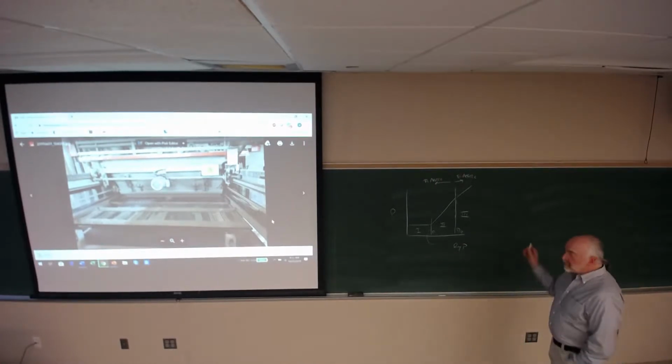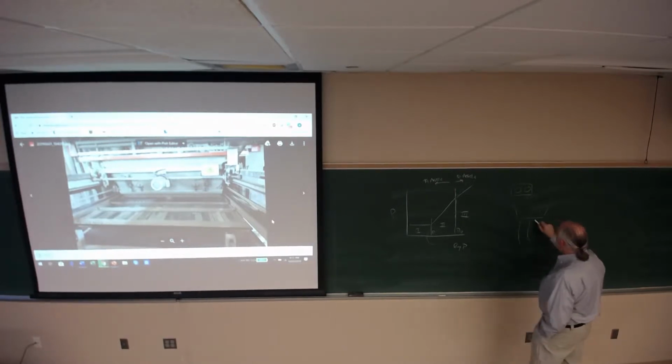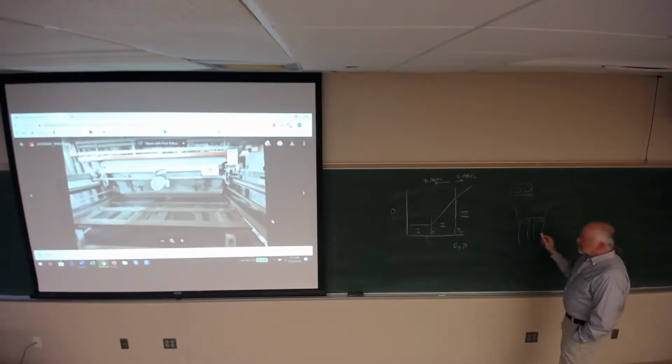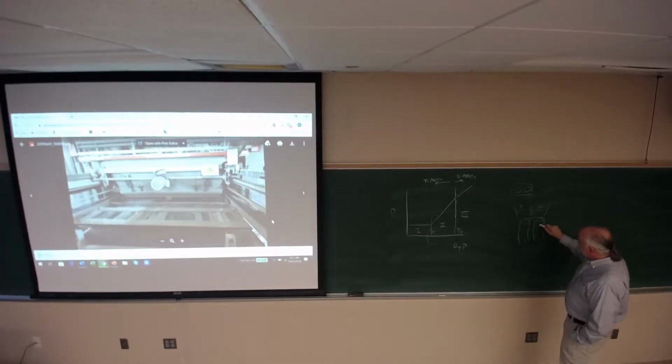We did a really simple experiment. They had a hopper that was set up, the top looks like this, had two tubes, and it was actually shaped something like this, and the tubes come out to feed a die. One thing we did was layer material in here, different colors, blue versus white, and then we looked to see what happened when it went into the hopper. The other thing we did is we fed it this way, blue on this side and white on this side, so you have blue coming down this one and this one.